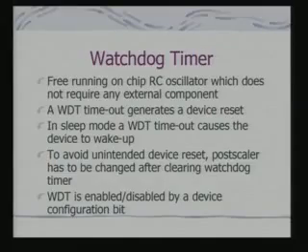Along with the timer, there is this watchdog timer, which I told you is a very important component for the majority of microcontrollers. Why is it important? Because when the microcontroller goes into some kind of undefined state because of a software error or a hardware error, you need some mechanism to come out of that error state, and this watchdog timer provides that facility.